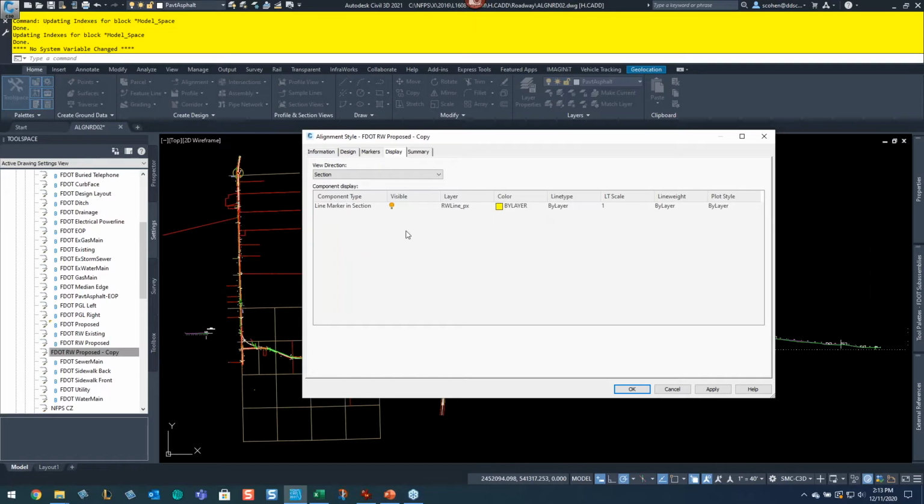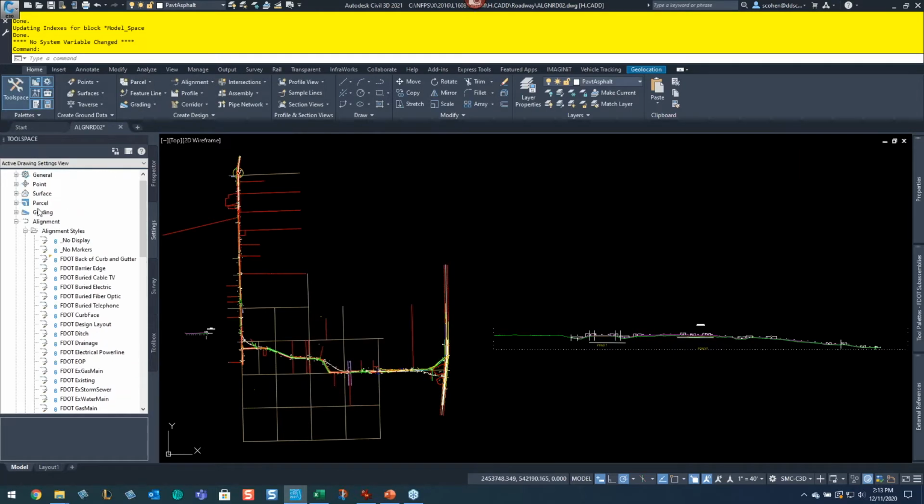It shows like a vertical line where that alignment is. And you can set this to specific colors like, hey, this is where I have my clear zone. This is where I have my right-of-way limits. This is where I have an edge of wetland. Whatever it is, you can uniquely define styles that will allow them to appear in the cross-section editor, which is very, very useful, okay?